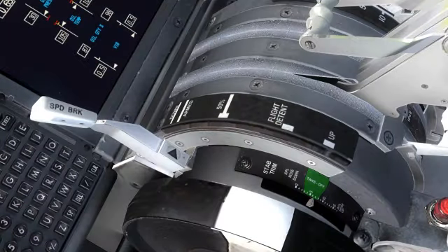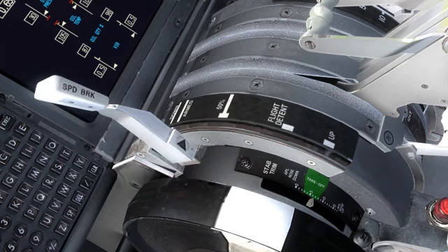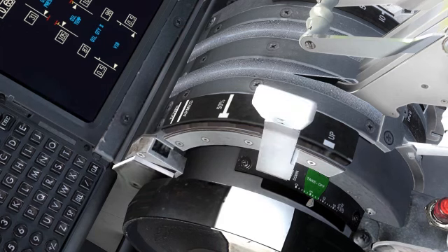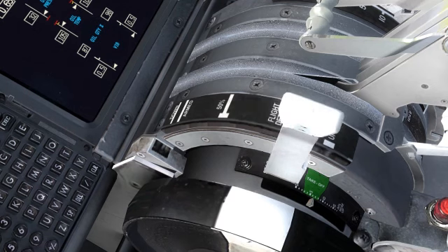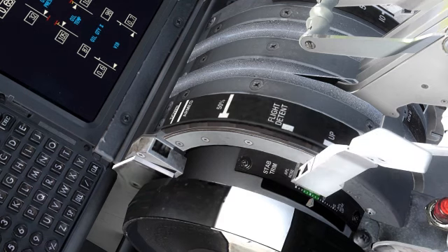Flight spoilers are controlled with the speed brake lever on the control stand. This lever has 4 positions. Down. All flight and ground spoilers are down and retracted. Armed. Arms the auto spoilers operation, which will be discussed further during this lesson. Flight detent. Flight spoilers reach their maximum safe extension in flight. Ground spoilers commence to extend upwards only if the aircraft is on ground. Up. All flight and ground spoilers are in their fully extended up position.